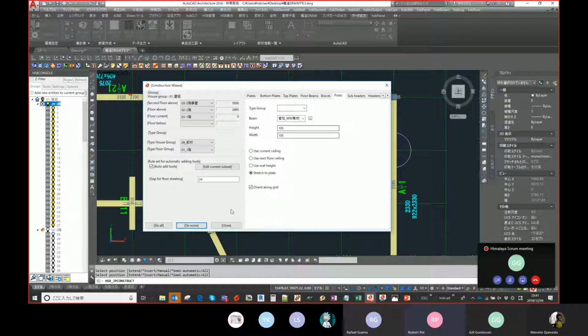What's this? Would these be like studs? No, well, it's called posts, and they have a special consideration in respect of tooling that has to be done. They're structurally important. And quite often this post will go through the bottom plate and through the top plate as well. So there are some things that need to be addressed, while the studs will really be positioned between the top and bottom plate.